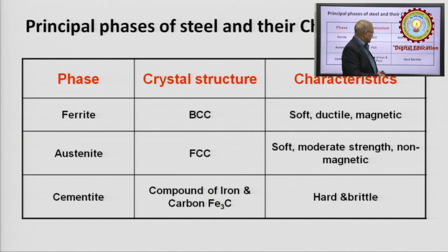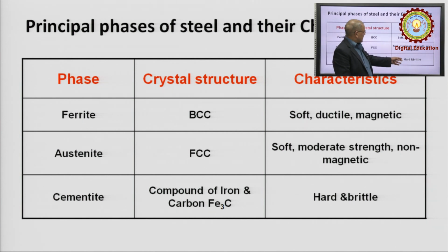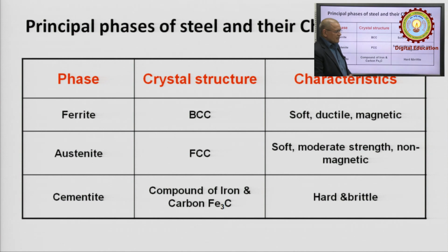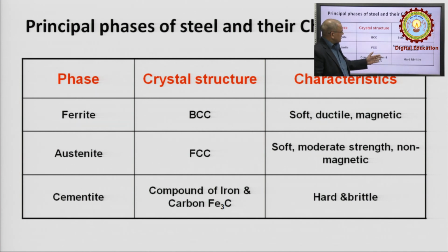Always remember, materials which are very hard are generally brittle. In the case of cutting tool material, where we carry out the hardening operation to increase the hardness, hardness is followed by brittleness, but when cutting tools are brittle, they will not be able to absorb the shock during cutting. So in that case we carry out a heat treatment, that is tempering. Because of tempering, some of the brittleness is removed at the cost of hardness, but the brittleness comes down. So the material becomes tough, that means it can be used for cutting purposes.